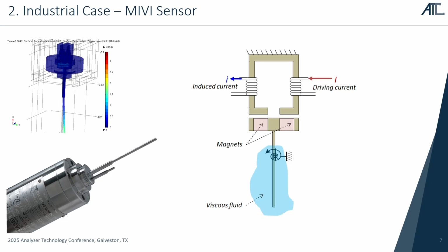This sensor is not influenced by external vibration. It is also a clean-in-place technology because as it vibrates, anything that is on the rod is getting cleaned or getting away from the rod. It is maintenance-free. There is no moving part. And we have had customers that have this sensor installed for more than 30 years, and they have had no issues with it.